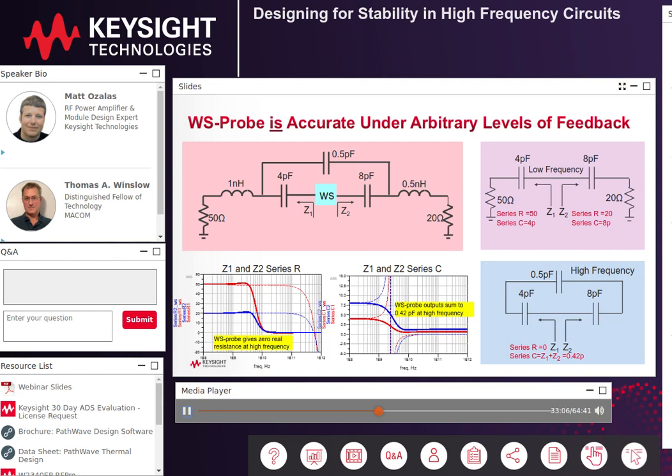And this is completely and necessarily predictable by inspection, given that we are asymptotically dealing with a closed loop composed of 3 series capacitors around the terminals of the probe. Also at high frequencies, you see the old S probe predict that both bidirectional looking reactances asymptote to 0, which is equivalent to 0 capacitance, which is also completely non-physical. So the old S probe is saying that it sees the high frequency source and load looking impedances to be composed of negative resistances and 0 capacitances, which is completely wrong by inspection.